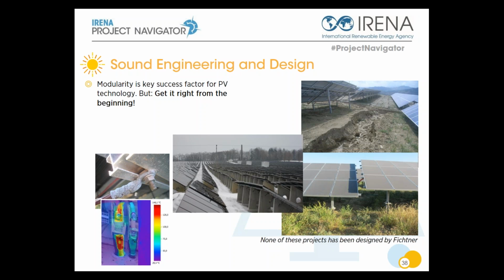You see at the bottom left side a thermographic picture of a connection of DC cables where the crimping hasn't been done properly, and you have temperatures up to 150 degrees at the connection point.